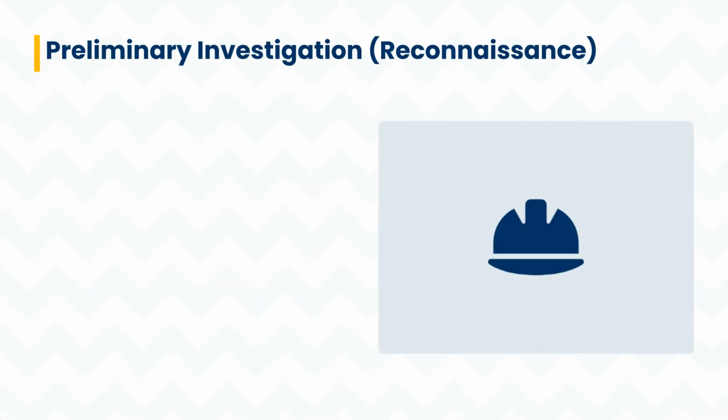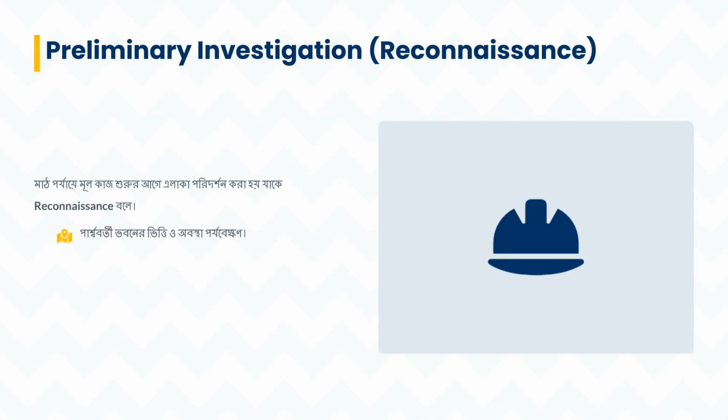Preliminary investigation, or reconnaissance, involves inspecting the area before starting the main fieldwork. This includes observing the condition of adjacent buildings, verifying coordinates and drainage, and identifying access routes for heavy machinery.